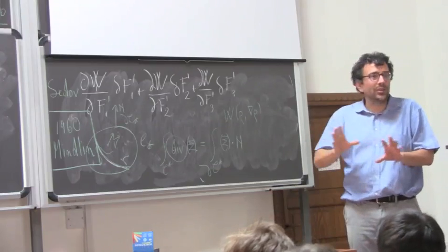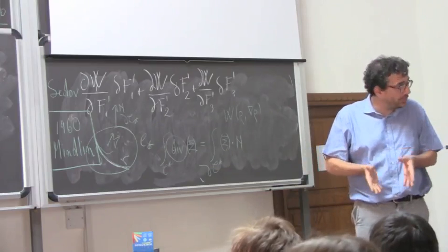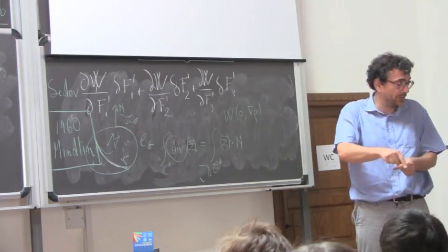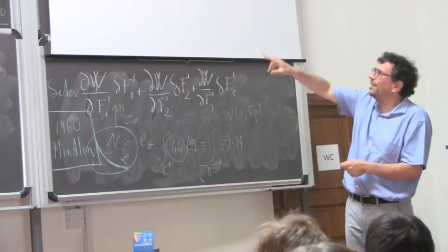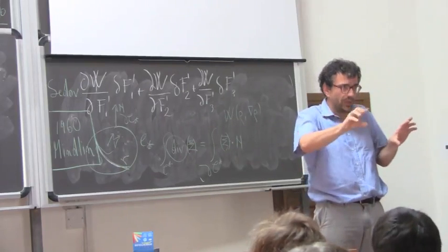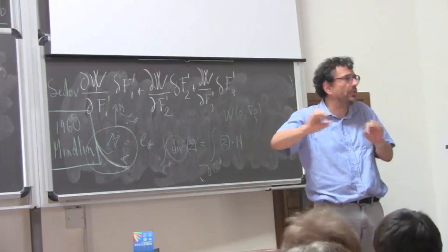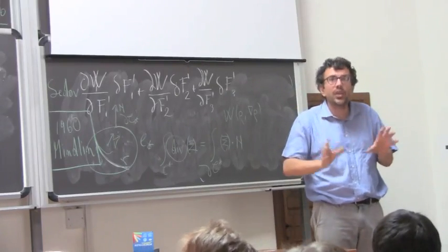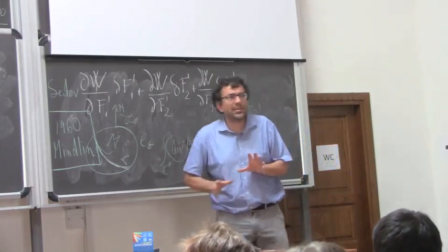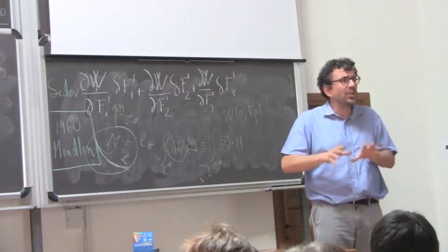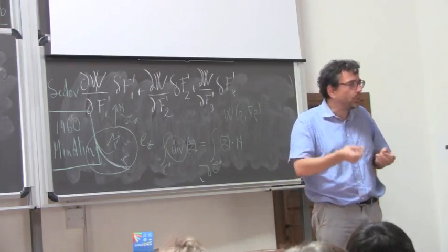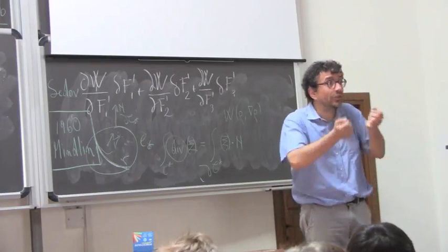So you could ask me why I wanted to integrate by parts. Because I wanted to tell you that the boundary conditions can be only forces per unit line, per unit surface. So when you write the total energy, you have the potential energy plus the potential energy of forces per unit volume plus the potential energies of the forces per unit surface. Otherwise, your model is not self-consistent. So this integration by parts is useful if you want to understand which are the correct boundary conditions to be given. But it is not a tool for finding the solution. Not anymore.